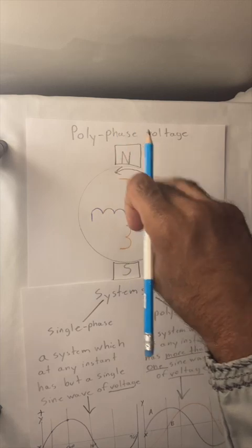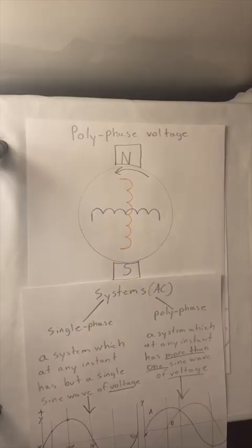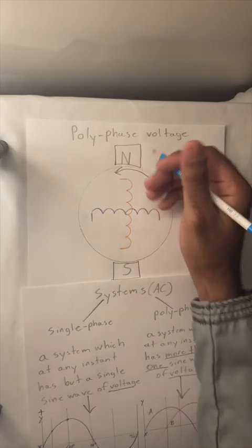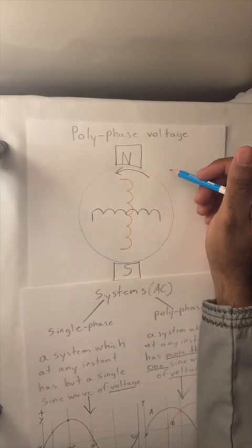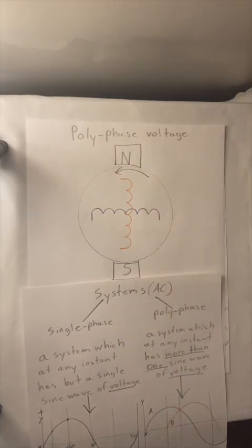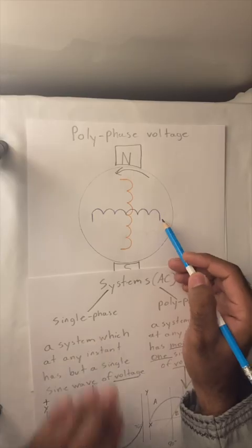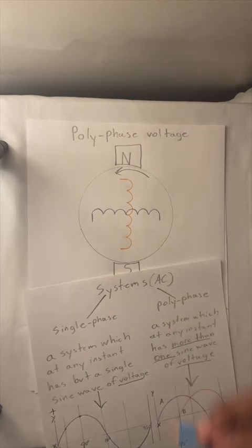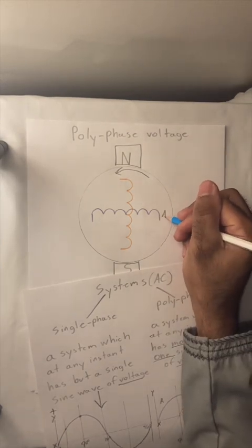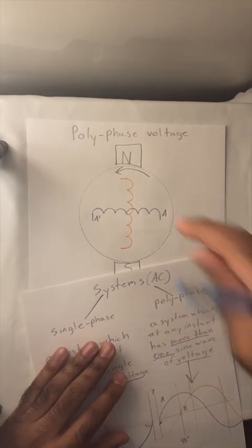The rotation could be either the actual field or the windings themselves. But in this situation, we're going to consider the windings to be in motion, and this is basically considered the armature. It would be rotated in a counterclockwise direction, which will generate what we call positive voltages. So we still have the single phase, similar to what was here, which we will label A and A prime.